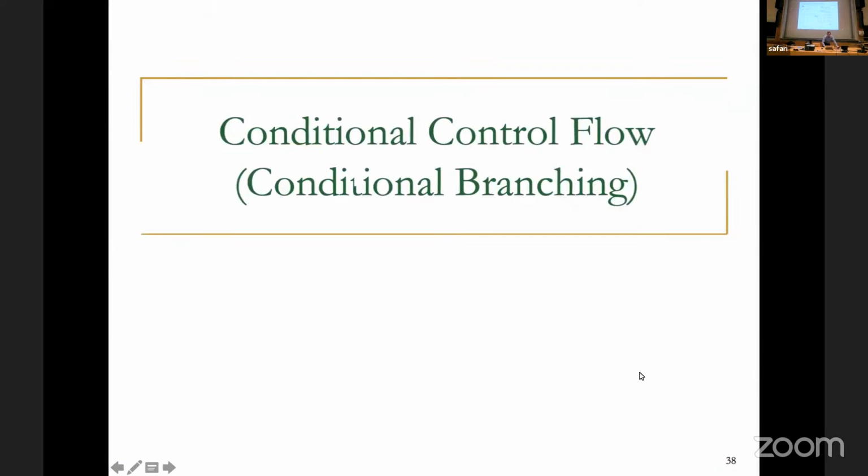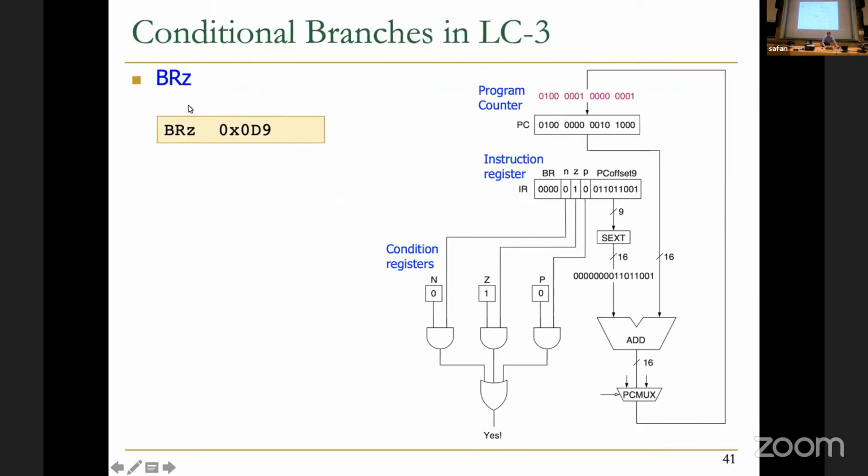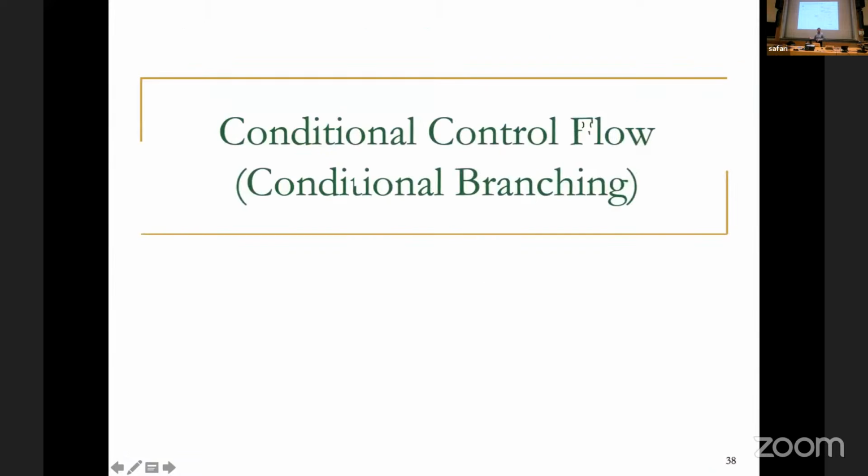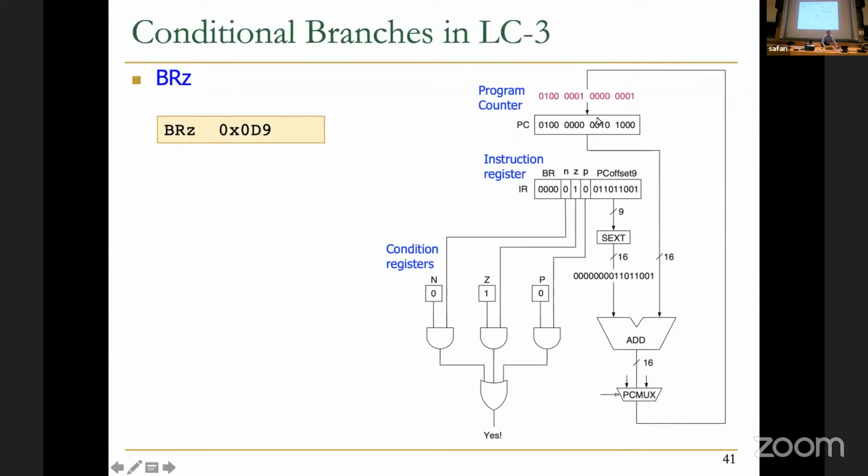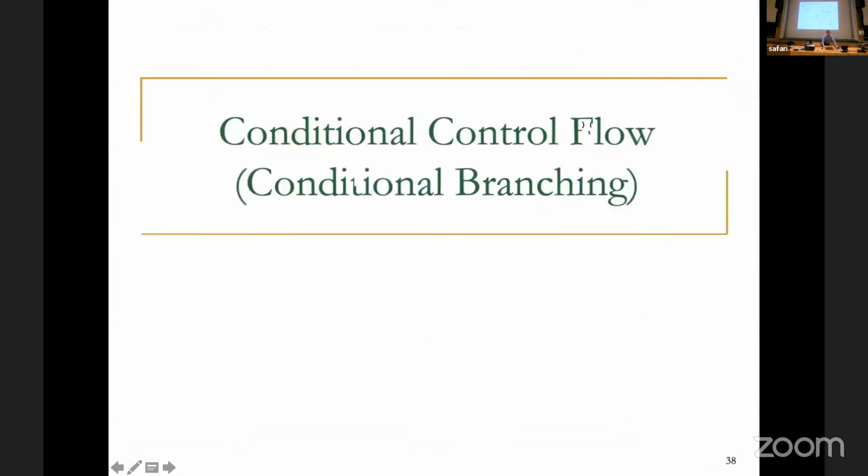You should select that particular address coming out because of this particular instruction opcode, and that should go into the program counter. So that, again, there's no magic. The data path elements need to be constructed such that you have a path from this adder that calculates PC plus sign extended 9-bit offset coming from the instruction register, and ensure that you actually write that value into the program counter. Makes sense, right?